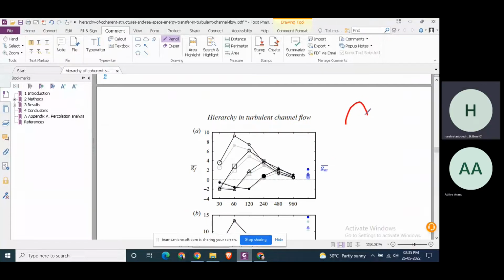So there are these cascades, right? Energy is flowing. What happens is large scale eddies dissipate energy, and small scale eddies absorb energy to keep the turbulent flow continuing. If it is a very large scale eddy and a very small scale eddy, they cannot interact with each other directly. First, the large one has to give energy to some small scale eddy comparable to it, and then it keeps getting smaller and smaller. So this shows us